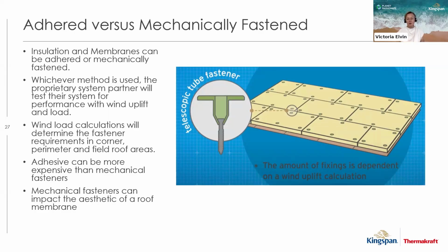The adhesive will be tested for compatibility and performance, and it can be more expensive than mechanical fasteners. However, mechanical fasteners can have an aesthetic impact that some clients don't like. That is part of the discussion when designing a warm roof system as to what the expectation is of a client of their roof and how they would visually like it to look.